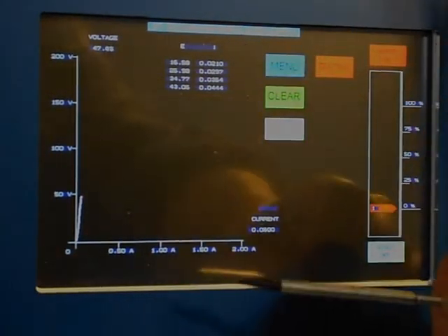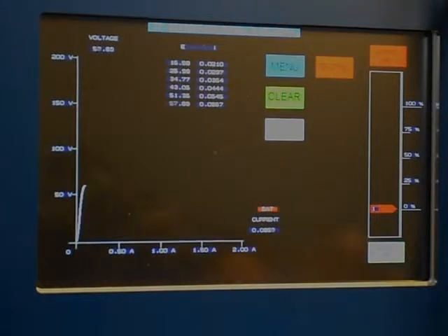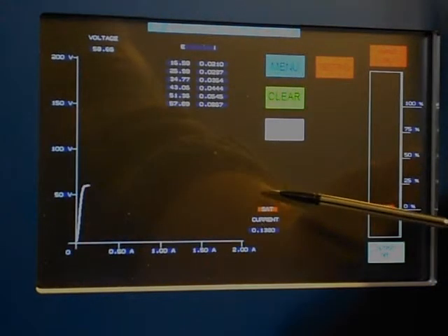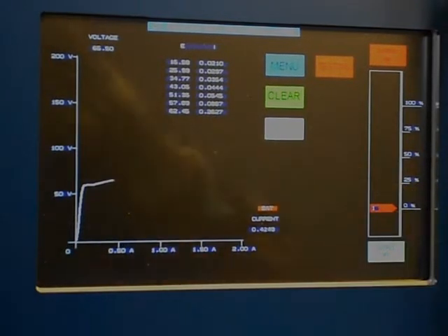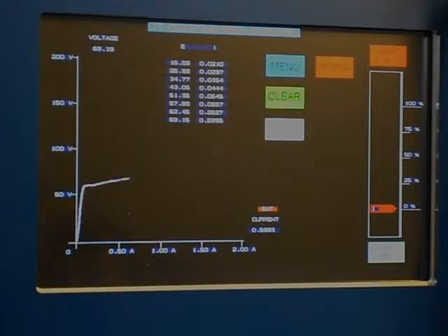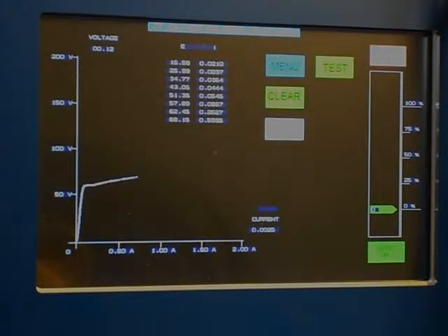So when it's done with the automatic test, you will have a set of data that you can record on your data sheet. When the curve reaches the saturation point, as detected by distortion in the exciting current, the little sat flag will light, indicating that you are in saturation. Notice the current has risen until we now have 750 milliamps, and then at that point it automatically cuts off, leaving the plot and the test results on the screen.